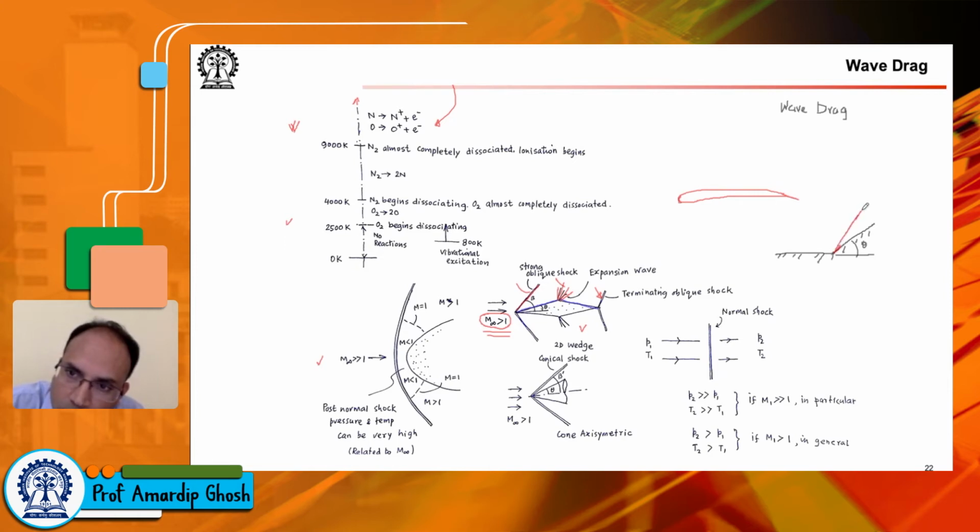It's called the wedge, the straight line actually. Pardon my bifurcating shock wave. This is just a straight line, okay? This is a straight line. And this angle is known as the shock angle. And this happens for supersonic Mach numbers. So if your M infinity is greater than 1 to begin with, okay?